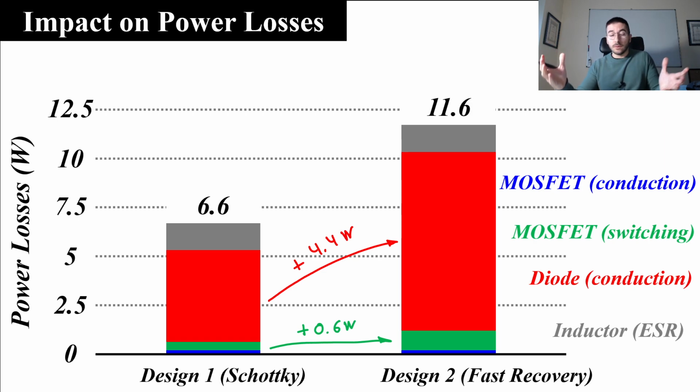So with this video we have seen what is the impact of changing the diode type in our buck converter design. So the conclusion is that Schottky diodes are the correct selection for our case, taking into account the voltage levels we consider, but perhaps in another scenario we don't have Schottky diodes for a higher voltage level, and we have to use another type of diode. So with this, we finish with the video.